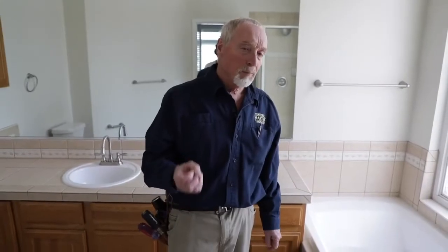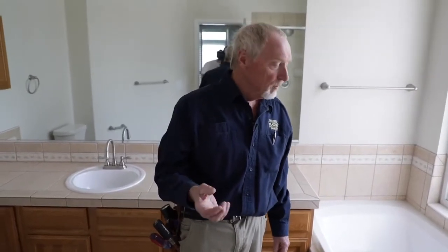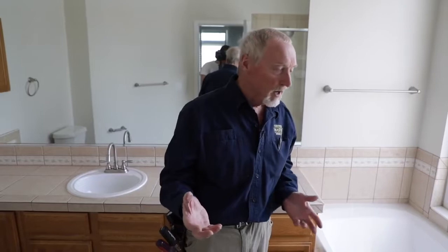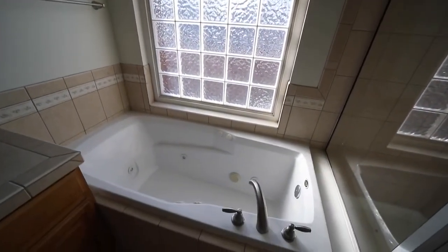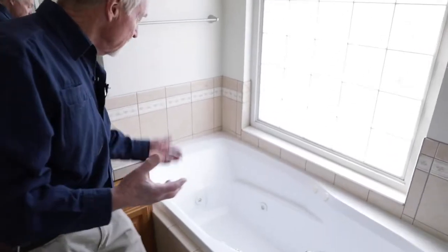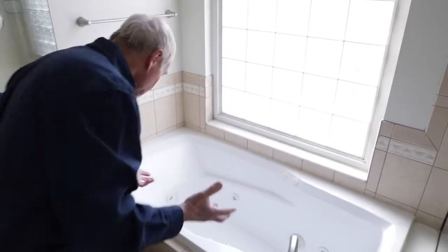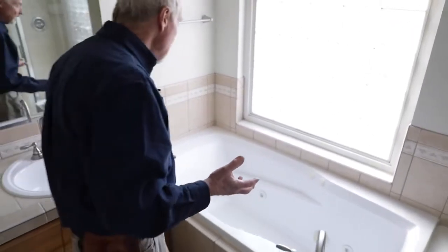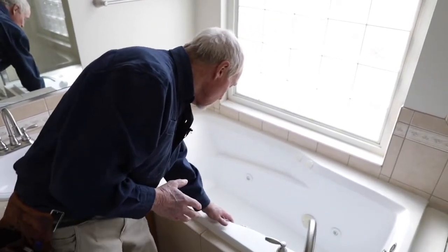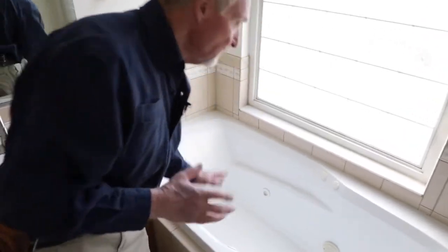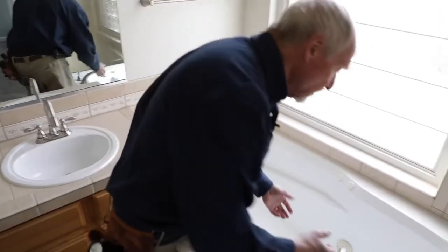So continuing 3.6 of our SOP on the plumbing section, we're in the master bath here now. And so among the things we have here is a jet tub. So with a jet tub, first of all, just do your visual inspection of it. I like to test the pump. We have a pneumatic switch here. Okay, I know the pump's working, so that's a good start.